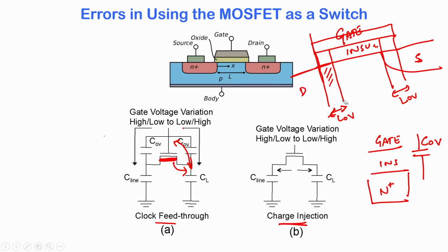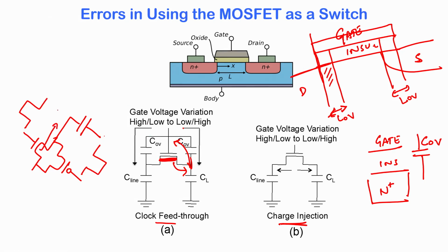In fact, for charge injection, a very useful technique is to have a complementary device, and you provide this complementary device with an opposing signal. So, let us say the gate goes on and off here, the clock drives the opposing gate. Which means that when electrons come out of this, an equal number of holes also come out of the complementary device, which is basically your PMOSFET, and that is your NMOSFET, and you have electrons and holes, and therefore, you do not have any charge injection. So, there are techniques to overcome these, but nevertheless, it is a problem that you should be aware of.